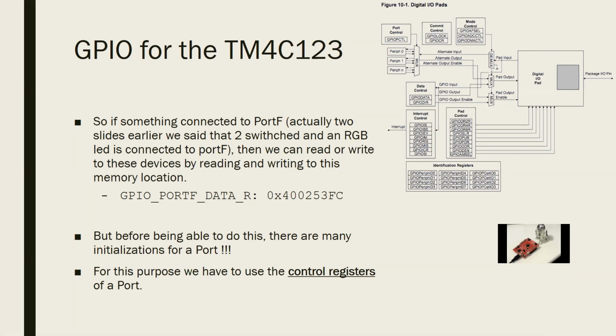There will be registers for that serial communication, and it will say, if you change this control register, you'll be able to send 8 bits of data in frames, and it will explain. So actually, hardware programming in very general is all about understanding those functions by understanding how to manipulate these control registers that belong to that functioning digital pad. Okay, that's pretty much a summary, I guess.